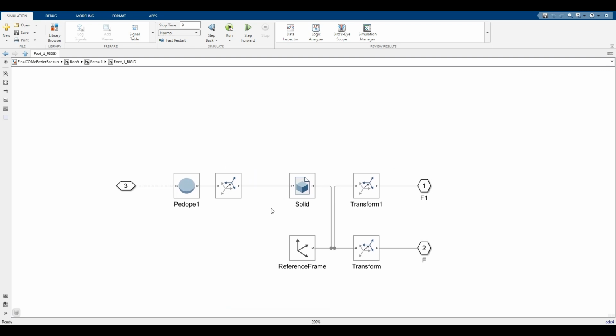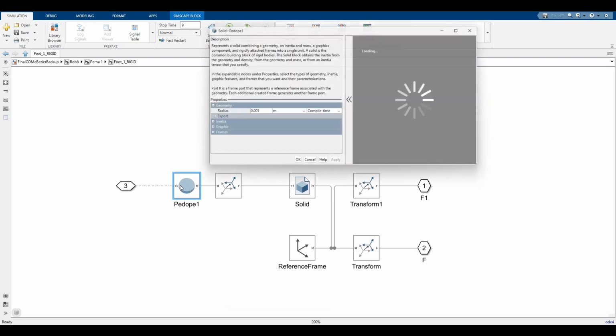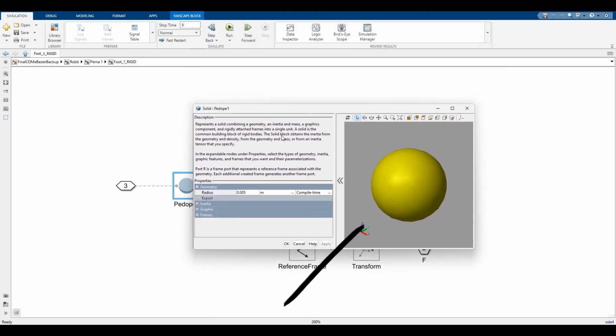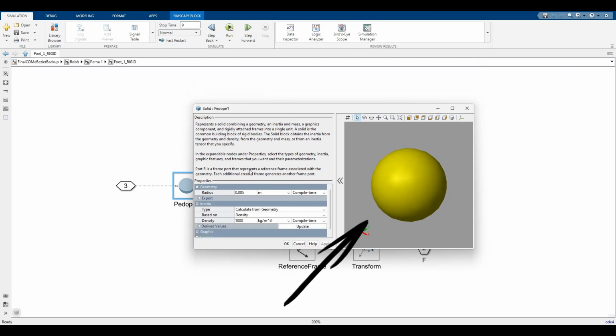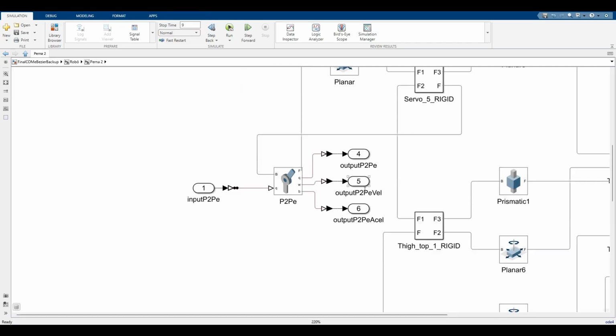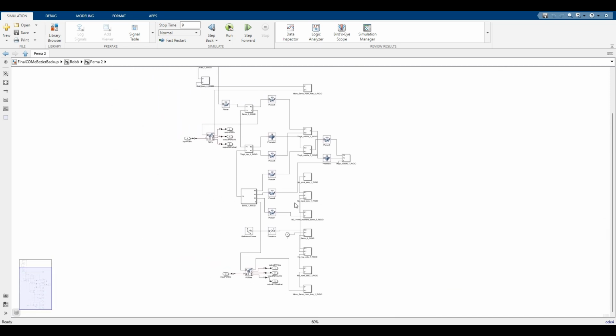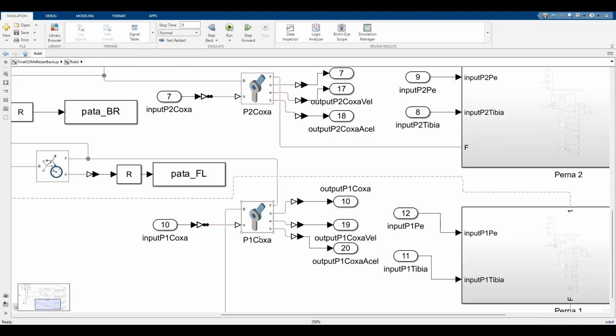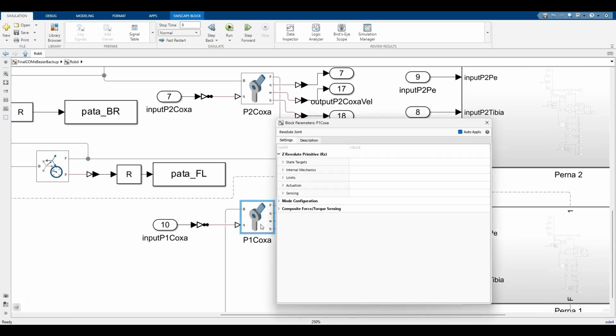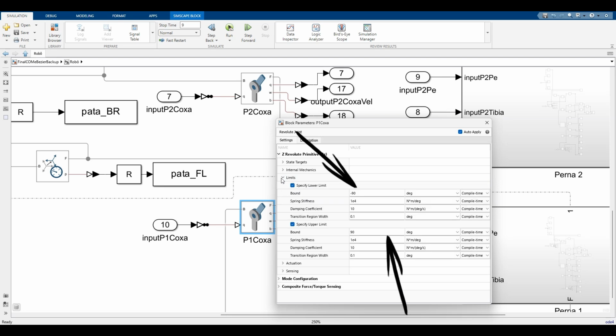To reduce computational load during simulation, each leg includes a 5 mm sphere at the tip to represent the contact point with the ground, which is used later in the analysis of the center of mass. All 4 legs follow the same structural block configuration, ensuring symmetry and modularity across the robot's design. In the thigh joints, we configured the physical limitations of the SG90 servo motors by defining their minimum and maximum rotation angles directly in MATLAB.